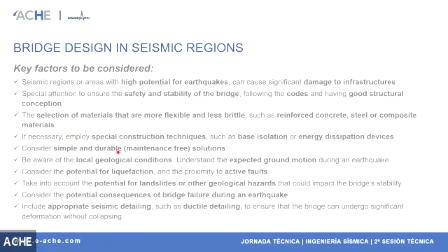Local geological conditions, of course, you have to understand, you have to know where you're putting your bridge. If you have potential of liquefaction, that is something we really need to take care of when designing a bridge with deep foundations on sand soils, mostly on sand soils, and proximity of active faults. Well, if you are designing a bridge crossing a river, normally you have a fault more or less active.